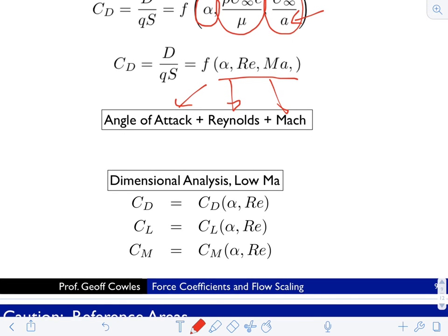So these three parameters are important, and because of the difficulties of really retaining Reynolds and Mach in the same wind tunnel experiment, for example, if you had a wing and you knew the conditions and you said, put this wing in the tunnel for me and run it at the same alpha, Reynolds, and Mach number, the good thing is that the drag coefficient that came out of the experiment is the same drag coefficient as your wing's going to have in real flight conditions.